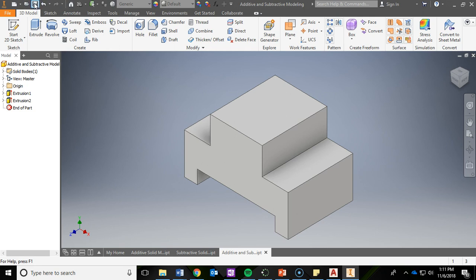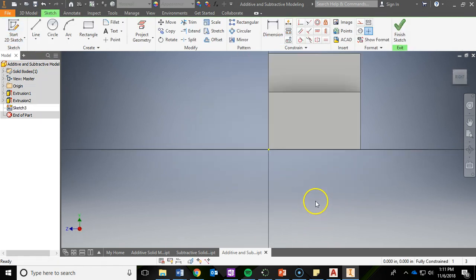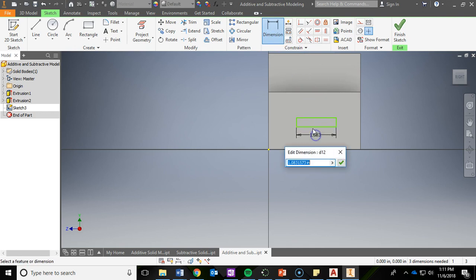And now I got one more part to add, which is on that right side face here. And this is going to be additive. So we did some additive, some subtractive, and I'm going to go ahead and put in a rectangle somewhere on this lower portion. Doesn't matter how big right now. I'm just going to hit escape to get out of that and add in all my dimensions. I know that this is 1.5. This is 0.25. So that's the size dimensions of the rectangle.